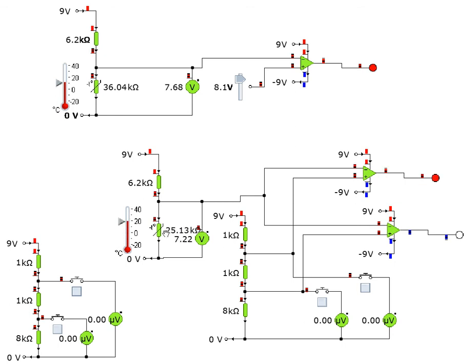Really, this is two separate circuits. You can think of the two comparators as two separate circuits. It just happens that they're using the same input to work it out. They're similar, but they're different. This one's comparing with 8.1 volts, this one's comparing with 7.2. So when it's cold, both op amps are off or low. As it gets hotter, first the top one switches on, and then the bottom one switches on.